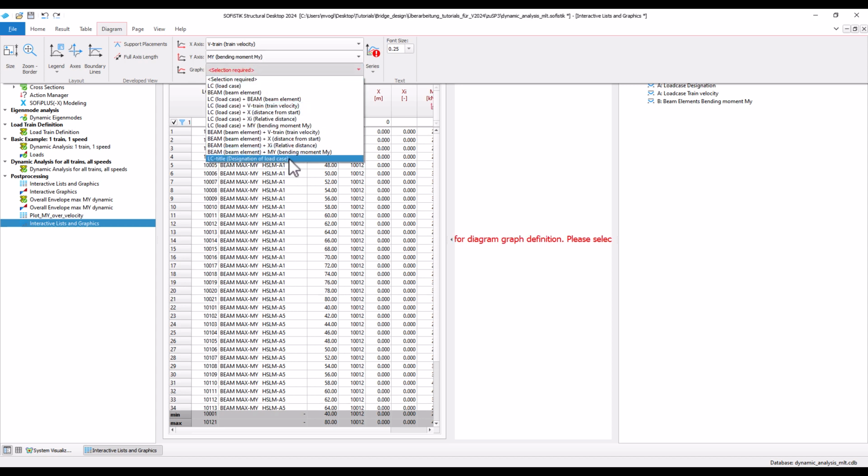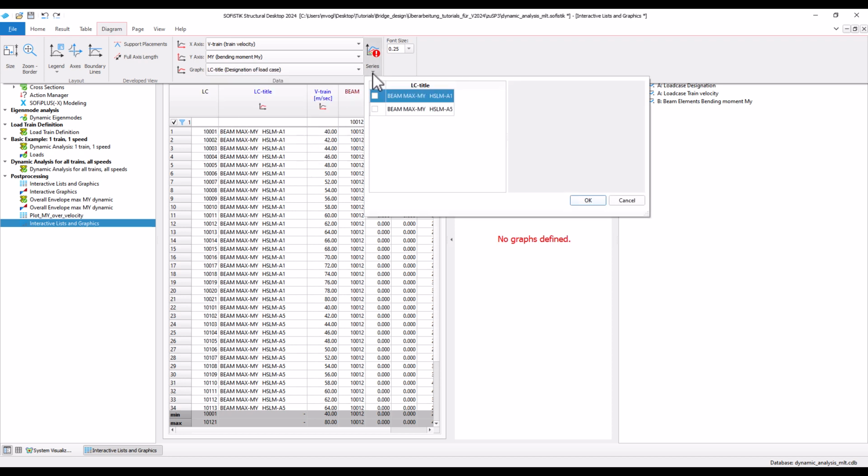For the creation of the plots, we need to specify which is the common information that makes individual load cases belong to the same graph. In our case, we use the load case title, which in the presented set is common for all envelopes belonging to the same train. Note that we have by intention set these titles in the MLT task for this purpose.